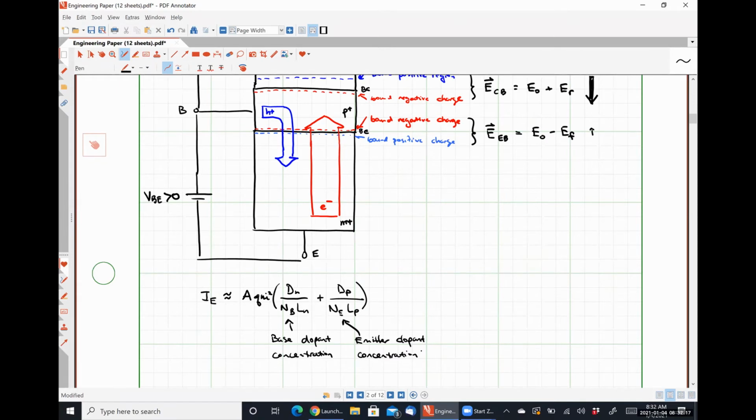This is just an educated guess, really, as to how this thing is going to at least partially behave. We have a forward bias PN junction, so it stands to reason that the current flowing in that region is going to behave like we expect a forward bias PN junction to do, right? Nothing too wild or crazy there, right? We have holes diffusing over, and we're also seeing that holes wind up being resupplied by the base, which means this gives us a base current in this direction. And since we have holes traveling down and electrons traveling up, that gives us a net positive current, IE, in the down direction as well.